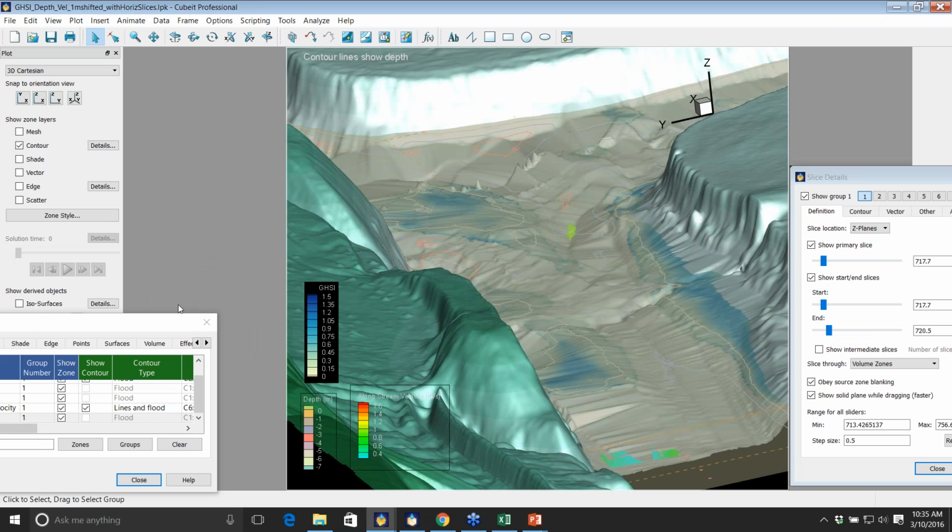And so what I am showing right now is the topography here. I have contour lines showing the depth of the channel, and then in the light blue tint, this is a different flow condition than before, but it's a habitat suitability index. One of the things to notice is this is one of the higher flow conditions. This was in February. The other one was in August at a lower flow. And my habitat suitability has moved, so I can look under different flow conditions.